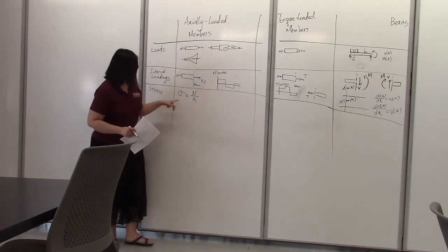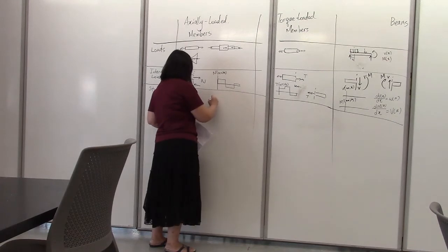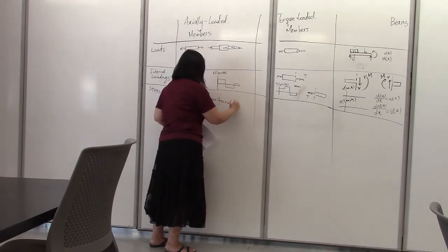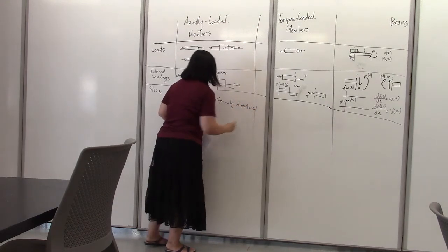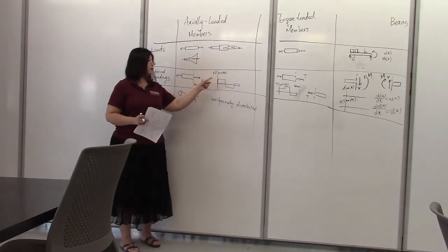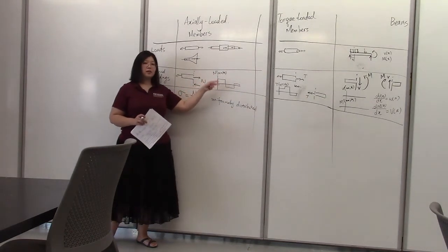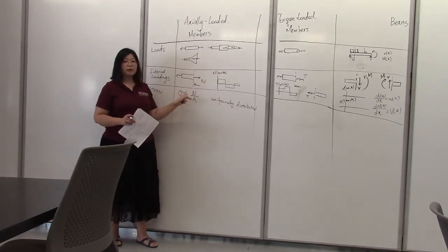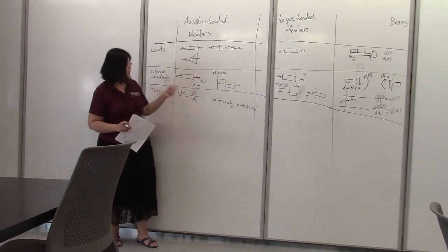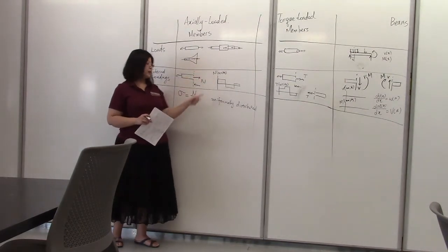Okay. So that's stress for axially loaded members, that is uniformly distributed on cross sections. When your N is different from segment to segment, then your stresses are also different on cross sections within each segment, because stress is directly related to the normal force N. Don't directly use the applied loads as your N.